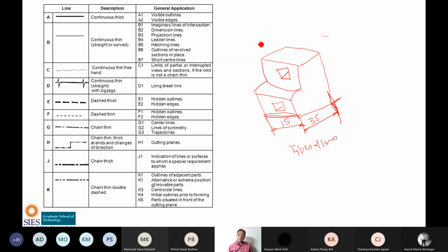I will draw the dimension like this. This is a light line, and this is a thick line, you can see this is a thick line, and I'm making it thick, exaggerating it. So this is a thin line, and this one is the thick line. Now whosoever is reading this will understand, okay, this is a thick line, this is a thin line, which means this drawing ends here. This is one of the reasons.